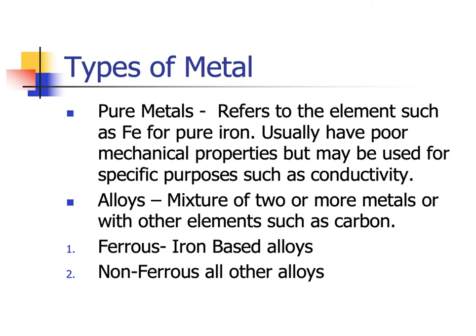Parts per million of oxygen in titanium will strengthen it significantly. It'll also make it really brittle. So you have to be really careful when you process titanium that you don't have even small amounts of oxygen in there. Also, nitrogen in many alloys is the same thing, even in steel. So ferrous is iron-based, and non-ferrous is all the other alloys.